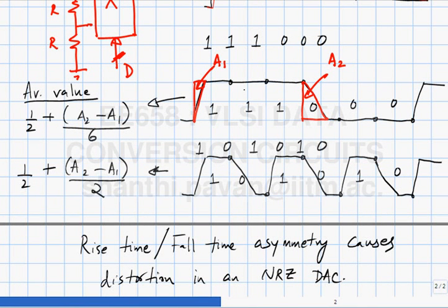Now, in practice, because it's nonlinear, if you put in a sine wave, what this means is that, even though you put in a discrete time sine wave at the input, and let's assume that the DAC has got enough resolution so that the quantization noise is very, very small, when you put in a sine wave you expect a sine wave at the output, right? But if there is nonlinearity, what will you get? You will get the sine wave and its harmonics, correct? Simply because this is nonlinear.